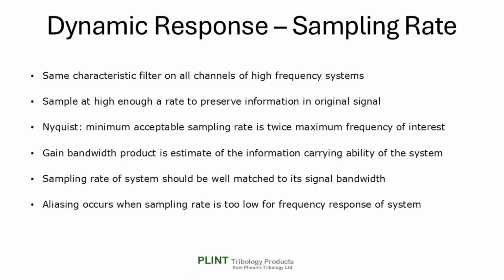If we are going to use filters, the same characteristic filter should be used on all measurement channels, especially in high frequency systems, to ensure that the information from different channels can be directly correlated and are not subject to differing time delays. When sampling the signals processed by a filter, it's important to sample at a high enough rate to preserve the information in the original signal.